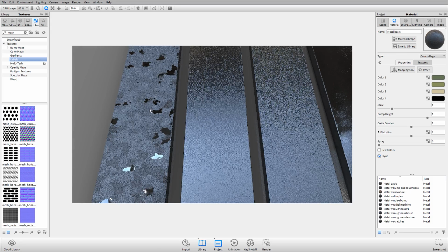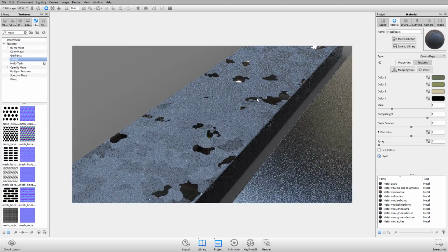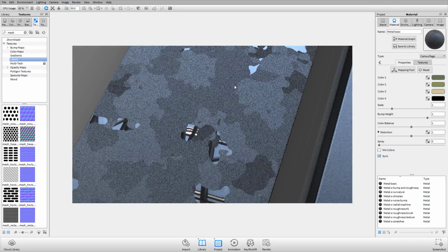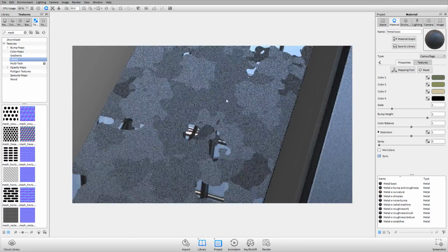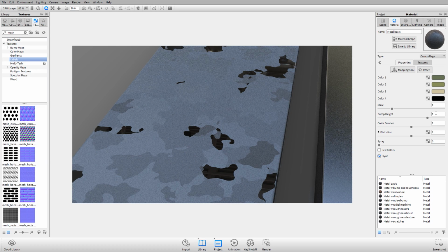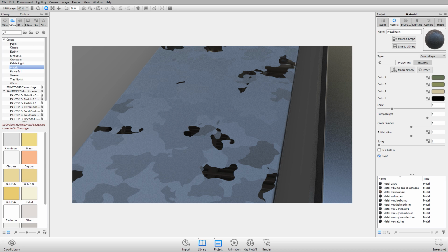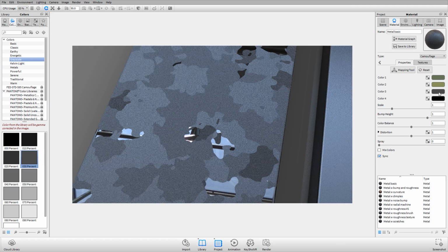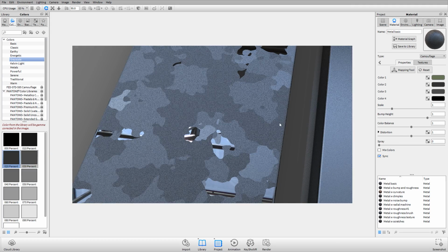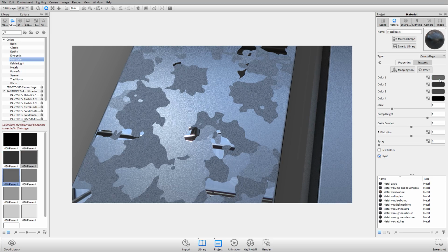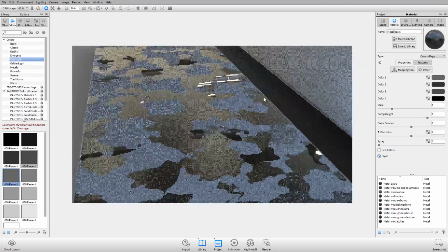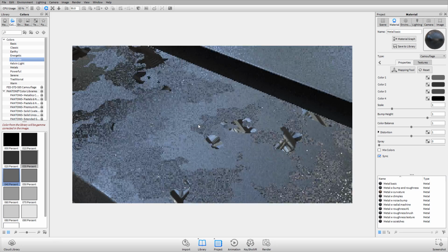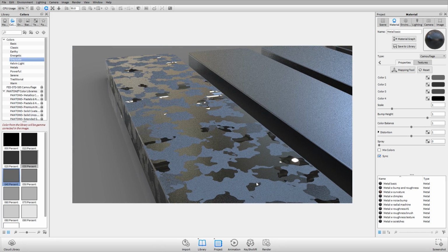Now you can see what that looks like with kind of the default settings. Normally, we use that as a texture to make it look like camo. But now what we're doing is we're defining the roughness using color values. And even though these are green, it's just pulling the grayscale value. So I'll go over to my colors. We've got some grayscale, so you can see 0 is black, which means it's perfectly smooth and shiny. And we'll throw in a couple of different grayscale values to represent varying amounts of roughness on the surface. And now we have a pretty slick looking material, right? We've got this crazy kind of camo. And again, that's with roughness.